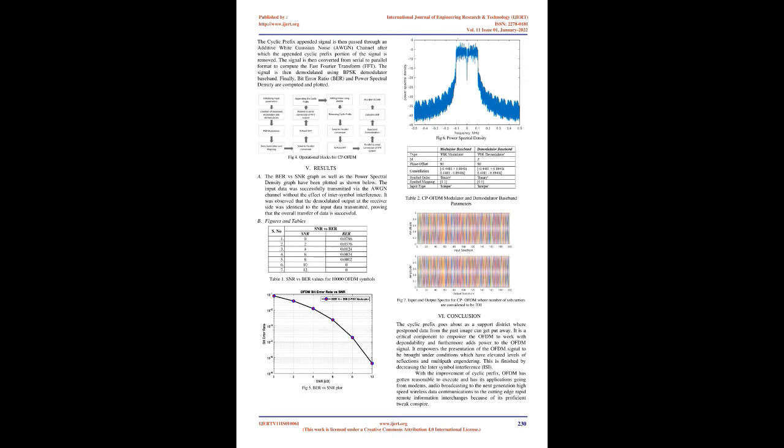The size of OFDM symbol has been considered to be the same as the length of IFFT/FFT. Cyclic prefix length is taken as 7% of the length of the OFDM symbol. If OFDM symbol length is considered to be 256, length of the cyclic prefix will be 7% of 256, about 16. Fig. 3. Block diagram of CP-OFDM.